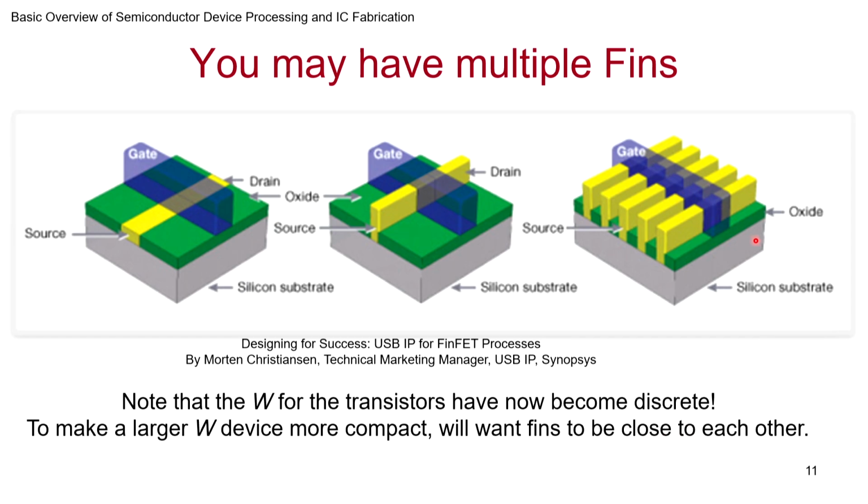Now, one of the key things in this is, if I have, let's say 2 fins, the space between the fins will end up making the size of the transistor larger. So you want to make a smallest transistor of a given size, but if you have two fins, depending on the spacing that is required to build two fins parallel to each other, the variable is called pitch, as we will see shortly. So that spacing will determine how compact these large transistors are.